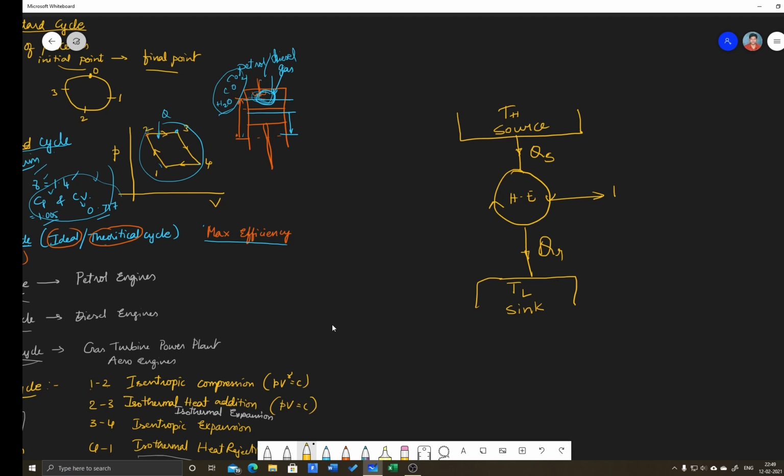You can extract heat from this. So here the efficiency of a heat engine is equal to 1 minus TL by TH if it is operating on a Carnot cycle. Only the Carnot engine is a reversible engine. In a problem, if it says a reversible engine is operating between, that reversible engine is a Carnot engine. In the next class, we will discuss the Otto cycle.